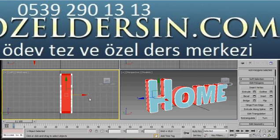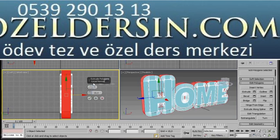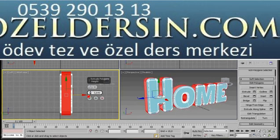Now let's add an extrude. So we'll click on the small settings box for extrude. Now here in the caddy we're going to select first of all local normal, and then underneath in the amount we're going to type in 1.5. Then press OK.